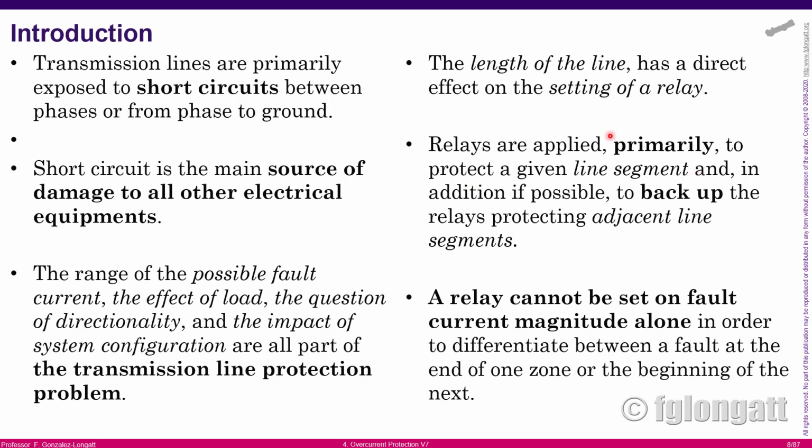What I would like to say is that relays are typically used as primary protection for transmission lines, especially for the primary segment inside the transmission line. However, those relays can also be used for backup protection, okay? One interesting thing is that overcurrent relays are useful.